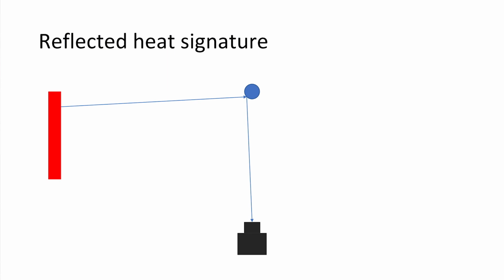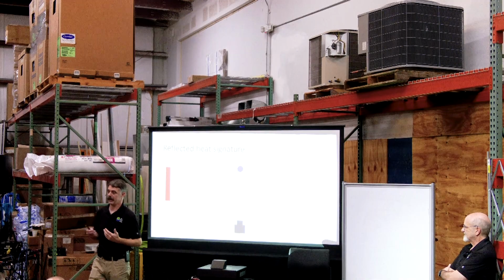This becomes an issue when measuring pipe temperature. If you're trying to measure pipe temperature, because we all work with pipes and refrigerant and things like that, and water and all this stuff, if you have a really shiny surface on that pipe or a very reflective surface on that pipe and you have a heat signature over here, you're only going to be able to get a really small spot that's actually an accurate temperature. And that's why we say this is a comparator.